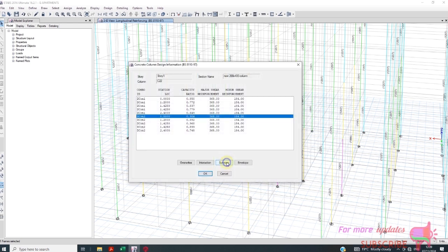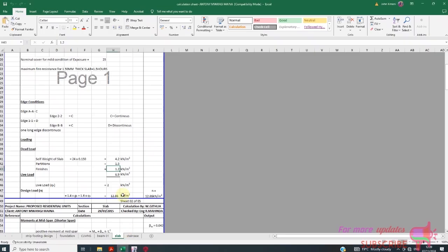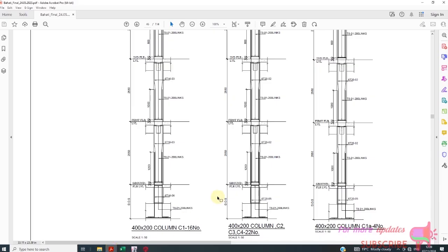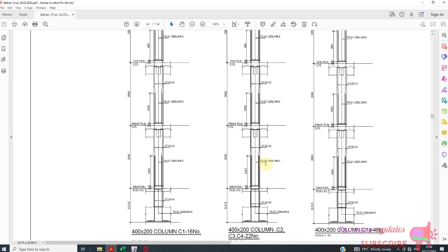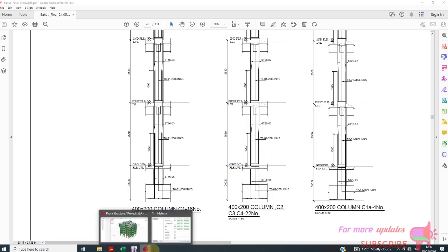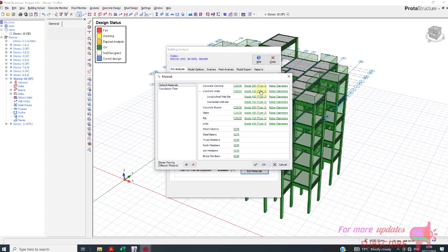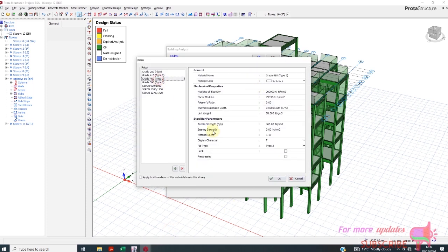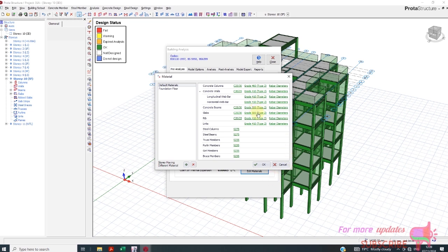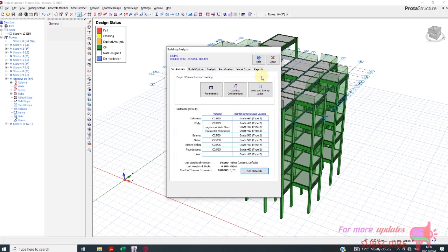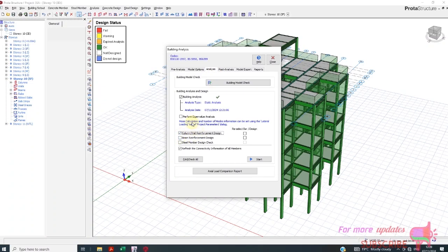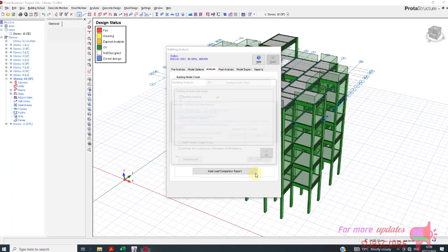Now all members are not overstressed, but we need 6 T20. This is evidence enough that the extra dead load on slab should be a value of 2, because that is what these particular engineers used. If I change this value to 460 for columns, then analyze, start.